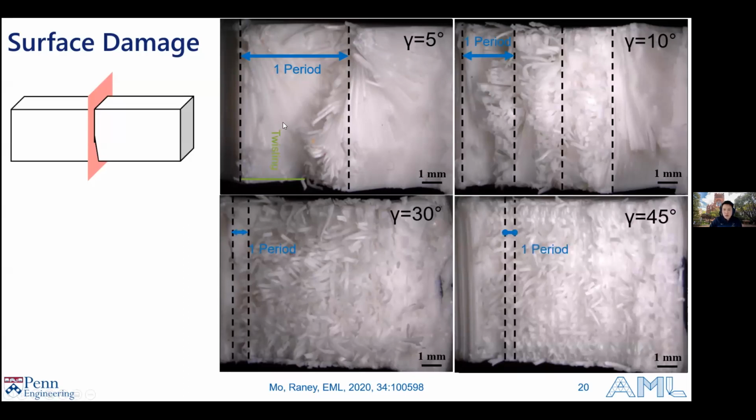And additionally, we can also observe regions of twisting crack propagation, which is indicated by, you can see these subsequent very nice layers of twist of these helical crack patterns. And then at some point, there is a change of the mode into the branching. You can see that there's actual breaking of these filaments, and then followed by twisting and branching again.